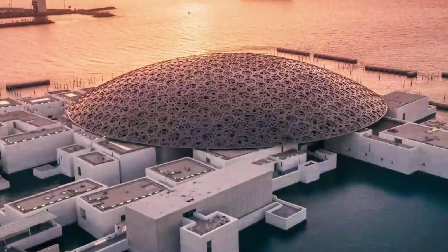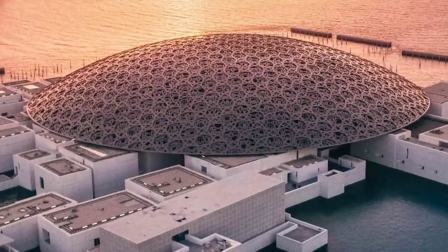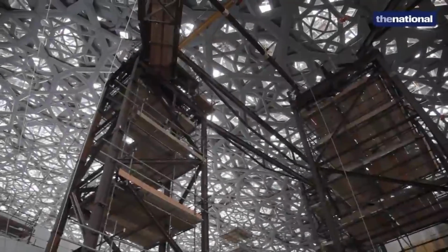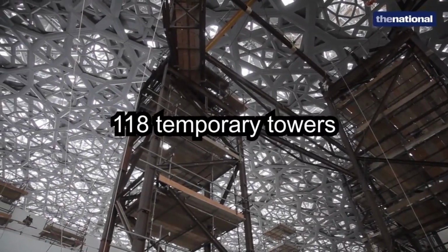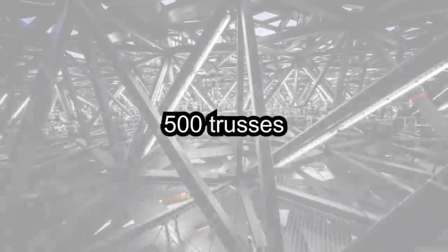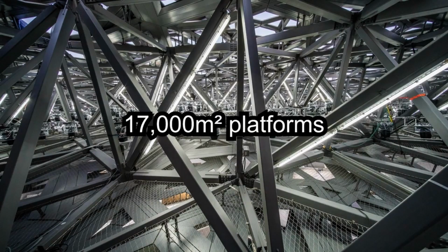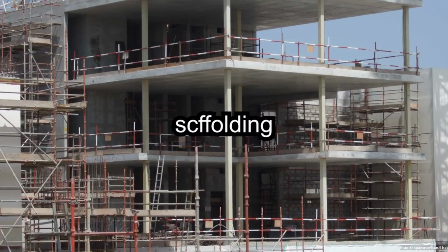From a distance, the dome of the museum at the time of construction seems to float above the gallery. But that is because of 118 temporary towers, 500 trusses, 30,000 meters of beams, and 70,000 square meters of platforms and scaffolding supporting it until its completion.